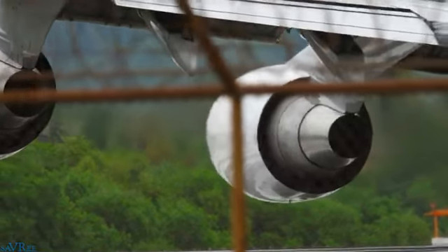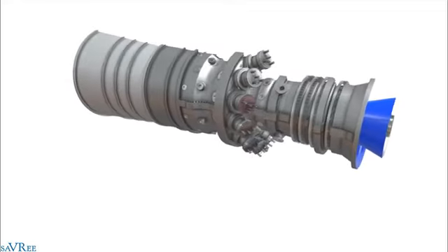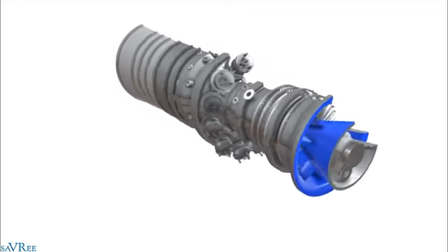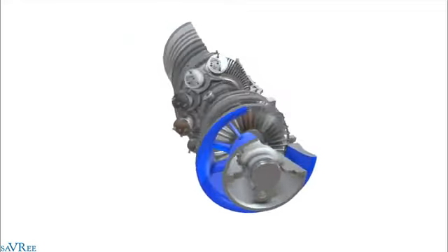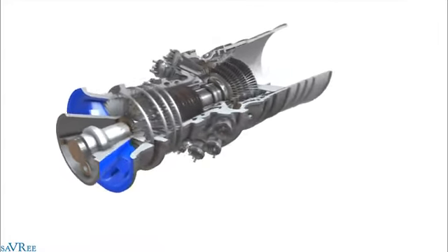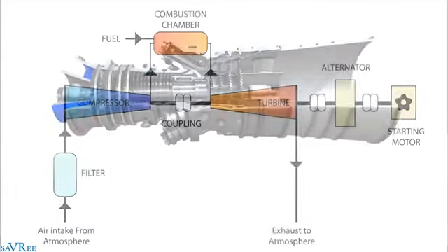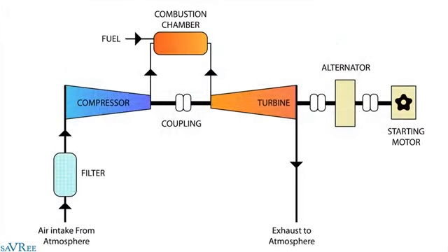In the power generation industry, we take a gas turbine and modify it slightly so that instead of just discharging the hot air directly out to atmosphere, we can instead perhaps reclaim some of that heat to make our turbine more efficient, and we can connect the central shaft, the single shaft of the turbine, to a generator. The generator rotor will rotate and we will generate electricity.